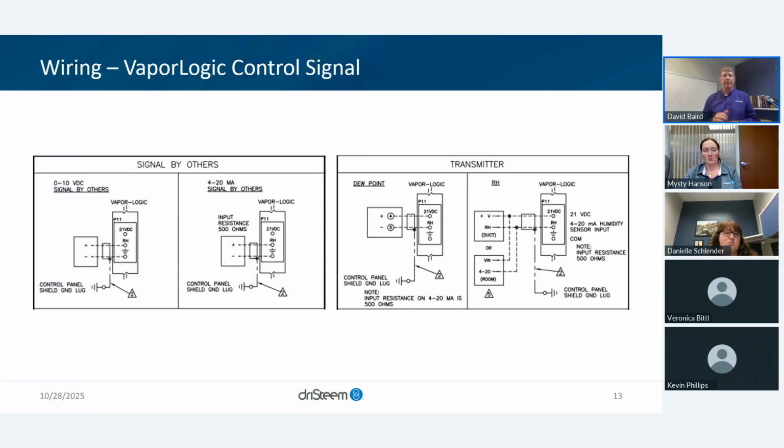The faster you're recording, you'll fill up that queue sooner, and then it keeps incrementing, losing the oldest information. That can be helpful, especially when you're troubleshooting. You can know everything that's happening: the state of the fill valve, the drain valve, the contactor, the input signal, airflow, high limit. All of that can be really helpful in a diagnostics mode, or when asking why my humidification system is not working as intended.